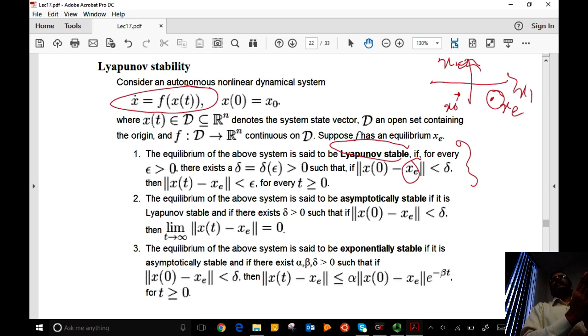It's not a limit cycle. It never goes to a steady state, but it wanders in a space, but in a subspace. It doesn't blow up, right? So when you have that kind of behavior, you can always bound that by a region delta, and the system will be considered stable. But it is not steady state. The time series is erratic, but it remains bounded. So that is essentially what this says. If the system is bounded, then it is stable.